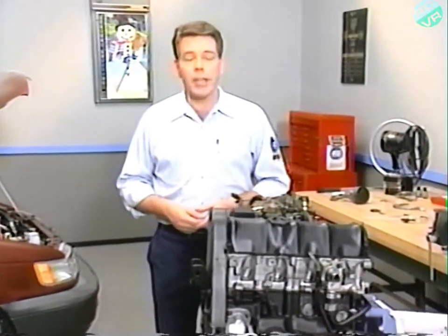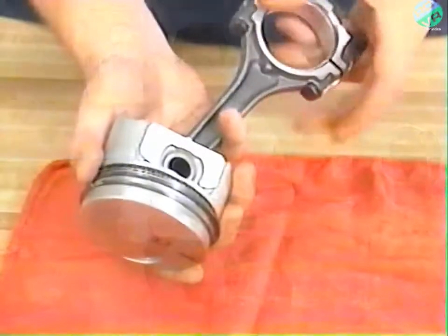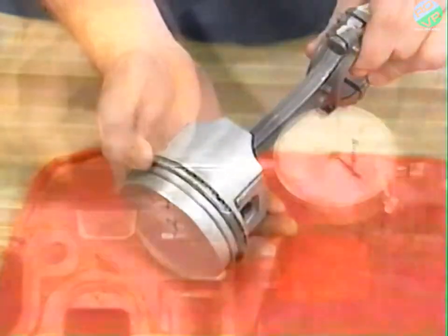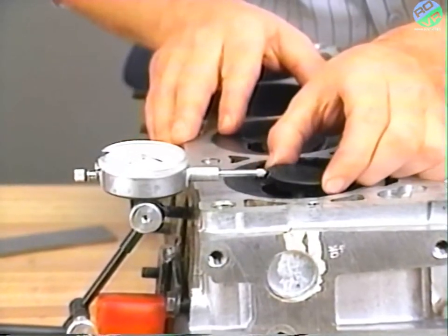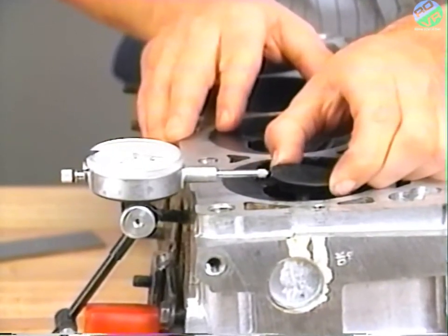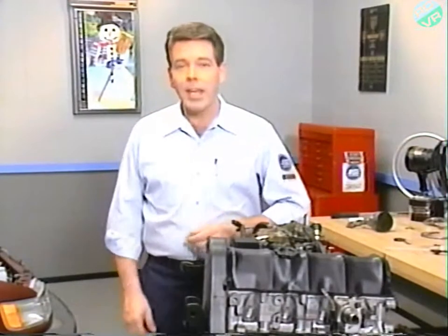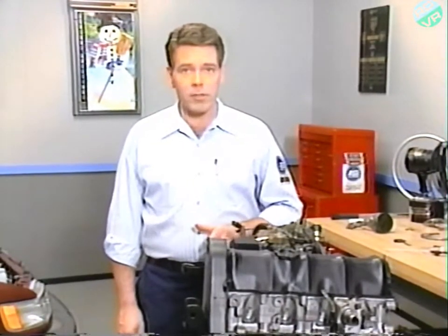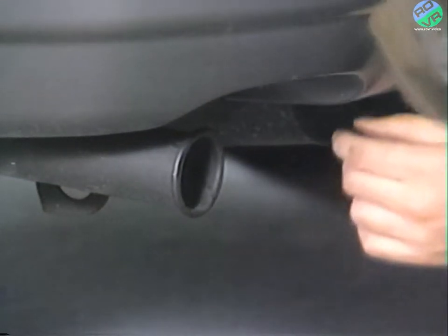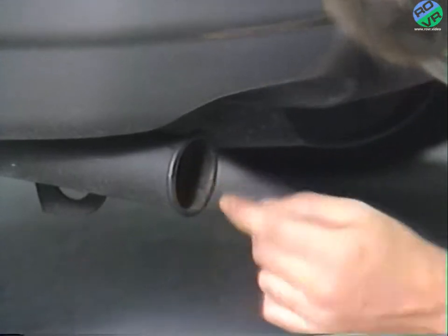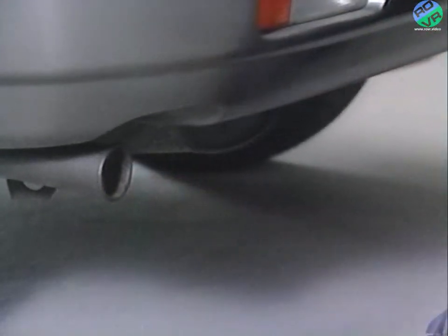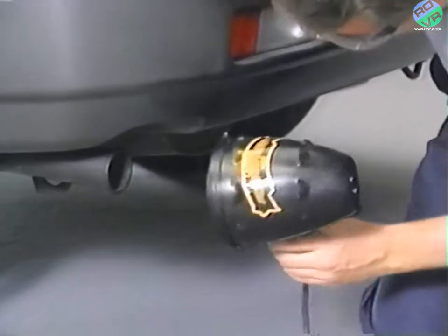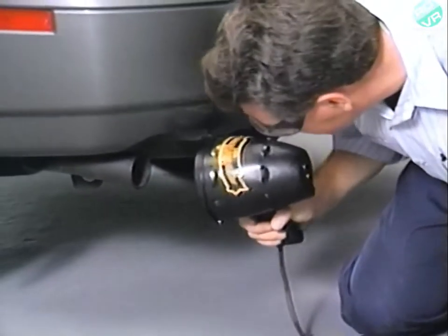This usually indicates an internal problem with the engine, such as broken or worn piston rings, worn valve guide seals, or worn valve guides. It may also indicate a blocked PCV valve. If oil is getting past the rings or through the valve guides, it usually shows up as a black oily deposit in the end of the muffler tailpipe, or as blue smoke out of the tailpipe. If you added the fluorescent dye, use the black light to check the tailpipe for leaking oil.